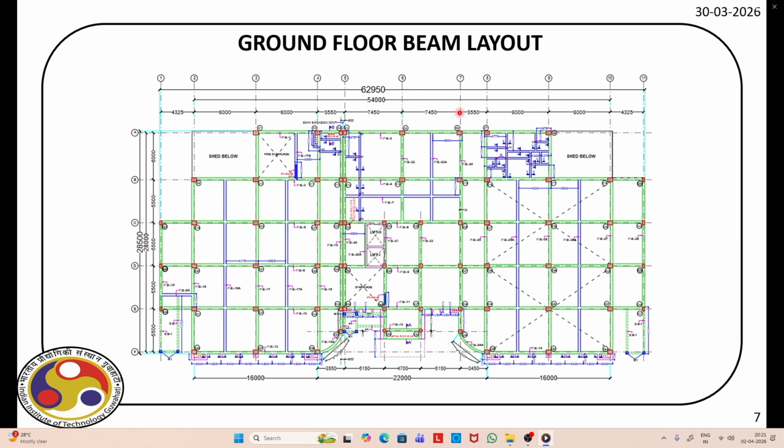Now you can see these grid locations. However, at this point there is an offset of the green beam. It is not centrally placed over this column. You can actually model with an offset, but again, because this is a simple demonstration, we will create a grid line along that 7 and make an approximation of grid locations there. However, as I said, you can further modify if you follow the same approach, and for every green beam you see, they are actually flushed with the outside of the column, and you can have a very detailed model with that offset. It is quite possible.